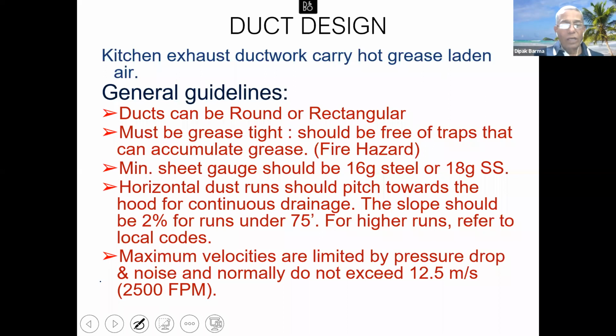Ducts can be round or rectangular. They must be grease tight and should be free of traps that can accumulate grease. Never have a sort of dip in the duct and then it goes up again. It will start collecting grease, which can be a fire hazard. So please avoid that. Minimum sheet gauge should be 16 gauge steel or 18 gauge SS.